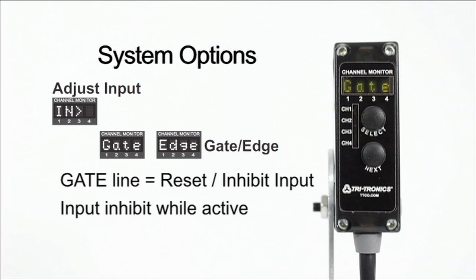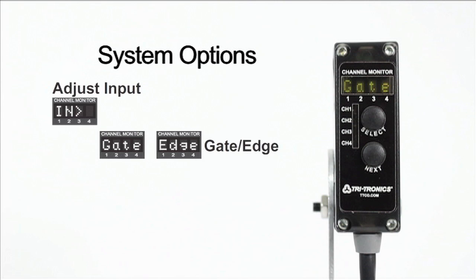Note that it does not inhibit the sensor's output, so timing events already in progress, like an off delay or one-shot, will run to completion. An idle to active transition will also reset all outputs that have been latched.